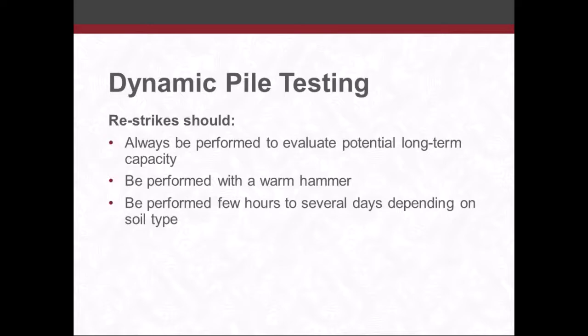And typically restrikes can be performed anywhere from a few hours to several days, depending on the soil type. So for the clays and the shales, typically 5 to 7 days is what we see in specs. For other soils, typically 24 to 48 hours is a typical time period.